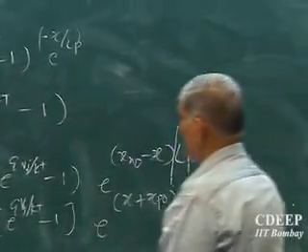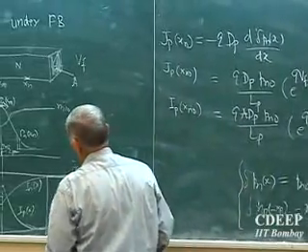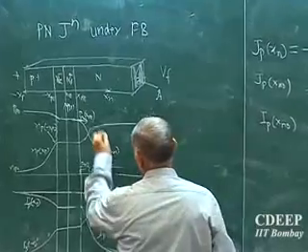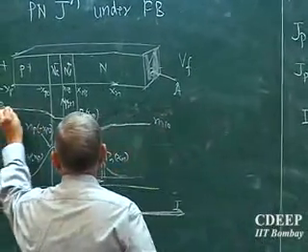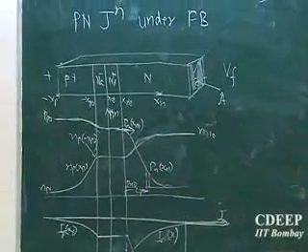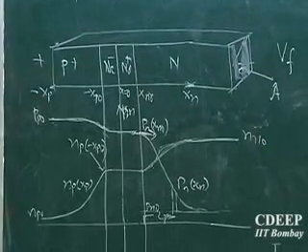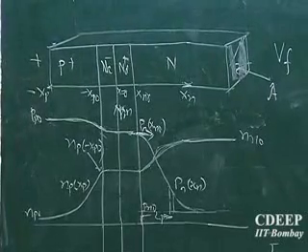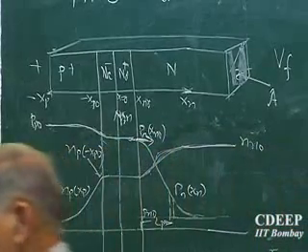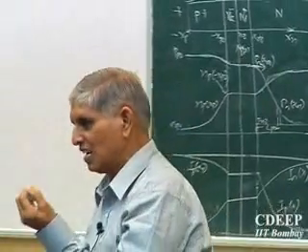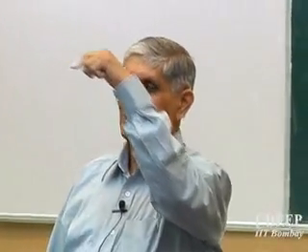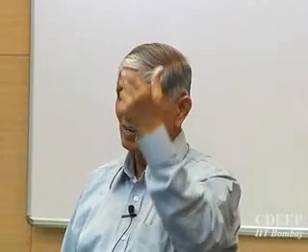Now this is very interesting as far as the theory goes. But you can see something I have done in my concentration profiles. Do you see something happening here? I intentionally showed you there. That means even when the holes reach from their equilibrium value closer to the transition region, they create a gradient. Why? Because within one diffusion length they will recombine, and if they recombine, they will create a gradient, and that is your whole point. By similar argument, electrons, as they reach closer to the junction from the n side, will recombine within their diffusion lengths and give you a small gradient, which itself is compensating the other current. Is that clear to you?